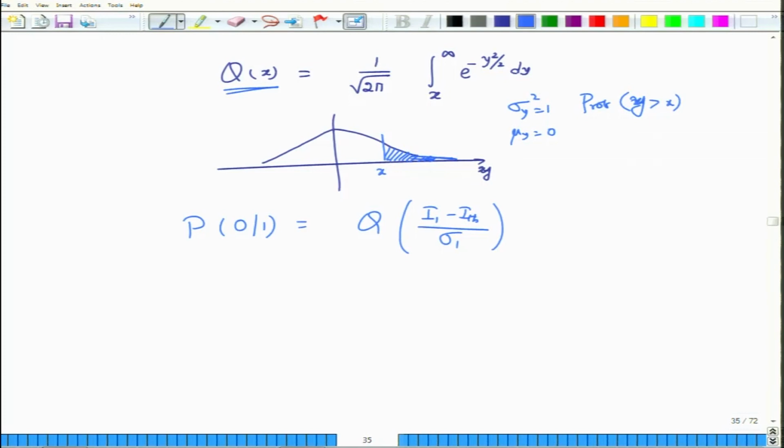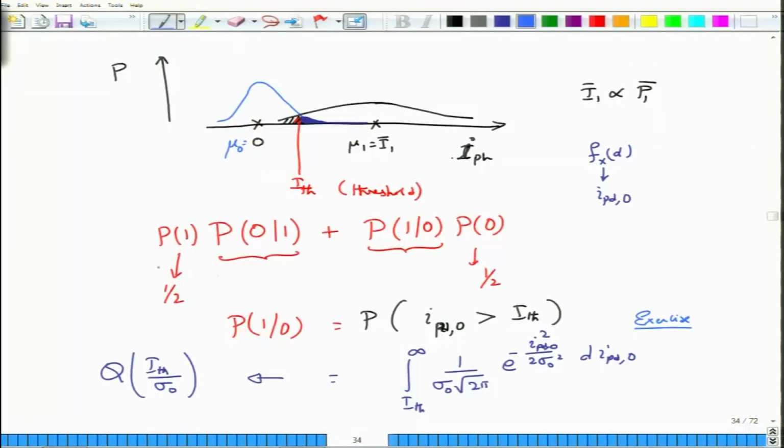So these are the two bit error probabilities that I wanted you to find out, and using these two values you can show that under infinite extinction ratio, so when ER is equal to infinity, not in dB but in the linear scale, then the bit error rate is actually this expression here. So this expression is the bit error rate, because it will tell you the probability of making bit errors when you transmit a 0 and when you transmit a 1.